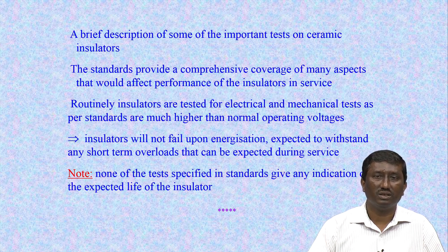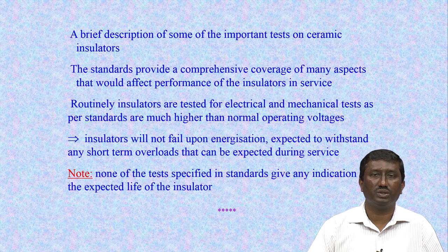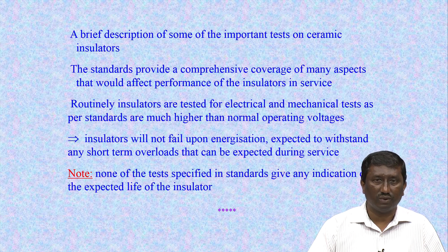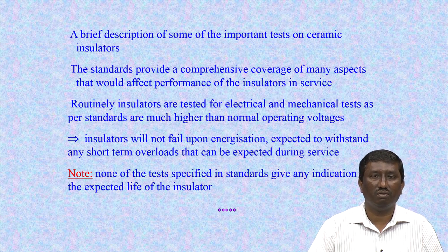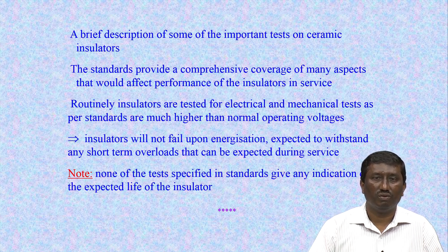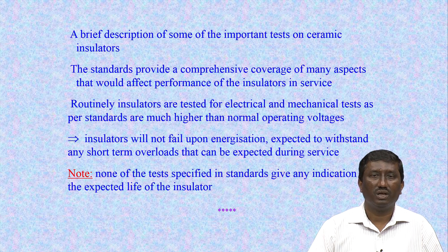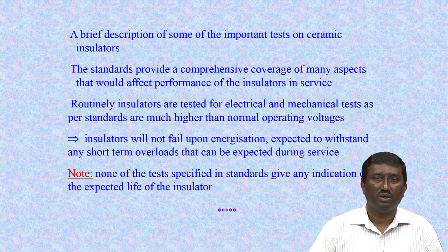So, the utilities and the manufacturers have to weigh the options on which type of insulator technology is to be used. Just by performing the entire test, there is no guarantee that the insulator string will last for the expected life, as there is no indication of the life expectancy of the string in the field from these lab tests. It should be noted.